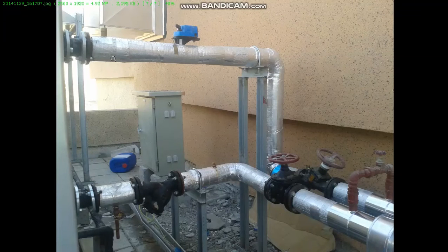Since we are calculating the pump head for the secondary chilled water pump, which supplies water from the chillers to the building, this is the supply side we need to consider. So what are the fittings we have on the air handling unit supply side? This is the gate valve, and this is the Y-type strainer. So we have two fittings, and this one is a two-way valve. You can use this for the primary chilled water pump head calculation, and this is the DRV, double regulating valve. Right now we consider only these two, the Y-type strainer and gate valve, because we are calculating the secondary chilled water pump head.